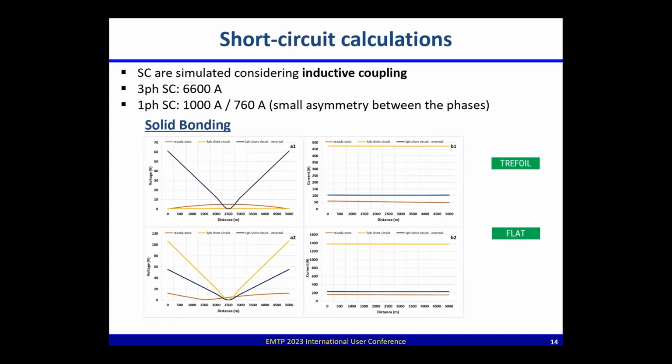Okay. But in the flat arrangement, what I'm saying is also verified, because we have an asymmetry in the geometry. You can see that we get again this V shape. Again, because here we have the inductive coupling, the same remarks as for the trefoil case can be used.